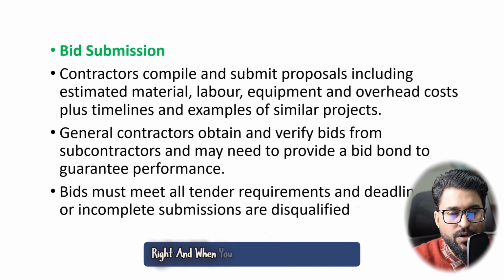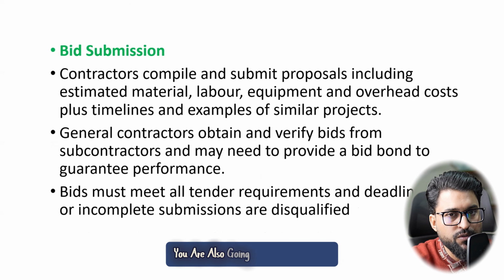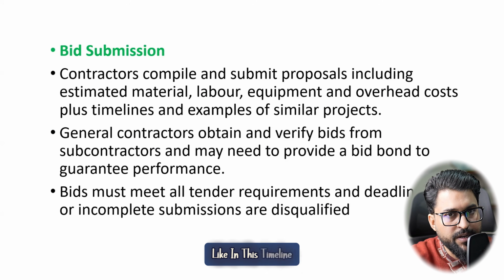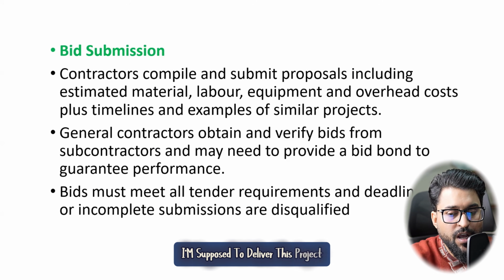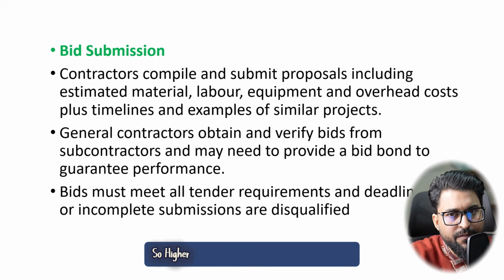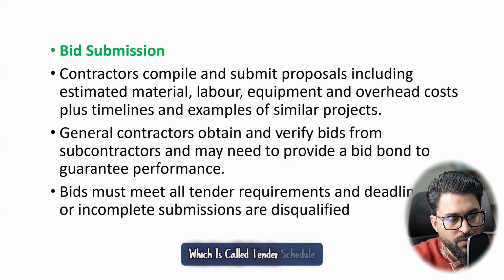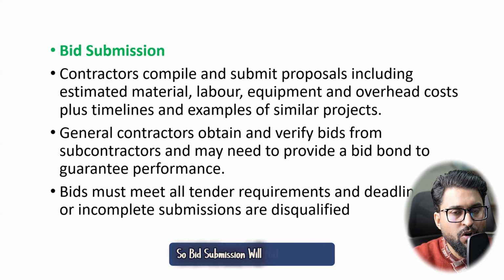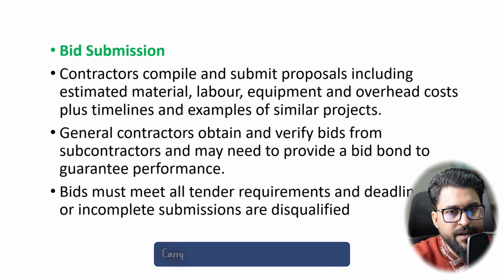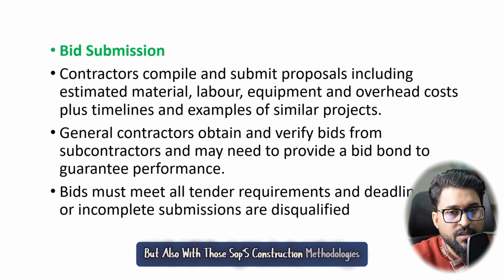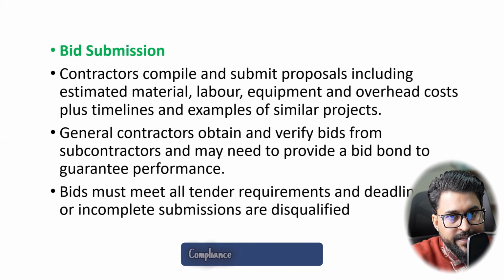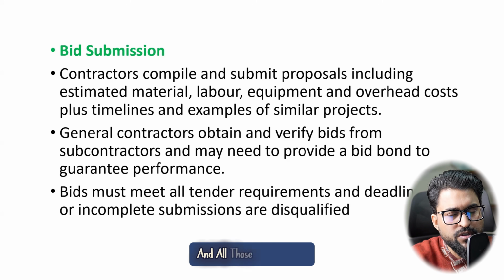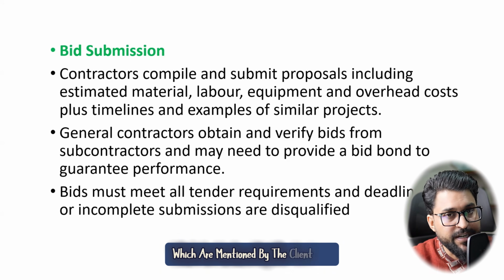And when you submit this bid, you also address the timeline. Like, in this timeline I'm supposed to deliver this project. How are you going to manage? So a higher level project schedule will be submitted, which is called the tender schedule. So bid submission will not only carry the BOQ submission, but also SOPs, construction methodologies, HSE, compliance, environment reports, and all those requirements mentioned by the client side.